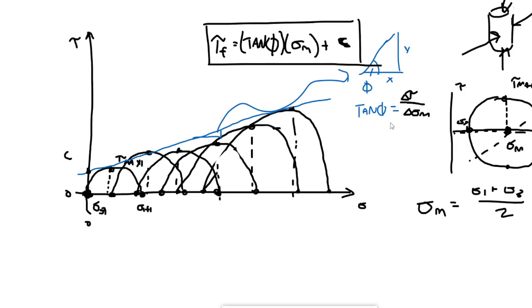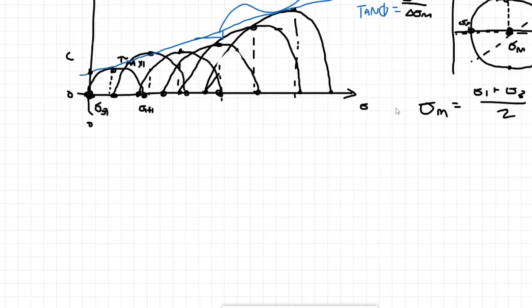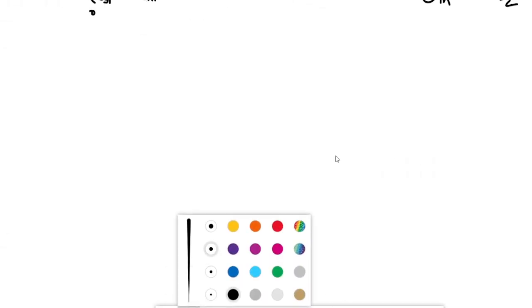Okay, last thing then, like I said, I'm going to talk a little bit about this internal friction angle, and why it's so important, why we bother talking about tangent phi, that angle phi. Let's just draw, say, this is part of a cylinder, and we'll do it super exaggerated, some big shear plane sitting in there. Your shear stresses are going to be acting in these directions, and then the angle in there is phi. This is the friction angle, the angle that these frictions are acting at to try to keep this rock in place so it doesn't fracture along that plane.